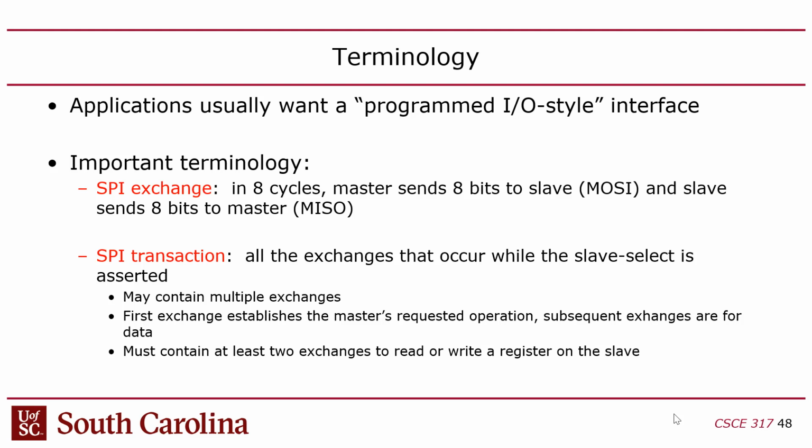The problem is that there is nothing in the SPI spec that defines what the transaction protocol is. The SPI spec just talks about MOSI, MISO, and basically how an exchange works. But when it comes to the transactions, that's up to the device that you bought that you want to talk to.